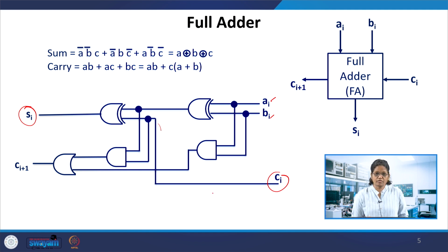That is the configuration we had done in the Verilog module. In order to minimize the number of gates, here we have used AB, and the output is ORed with the simplified term, A XOR B, AND C. This would also mimic the same behavior; the logic would be similar.